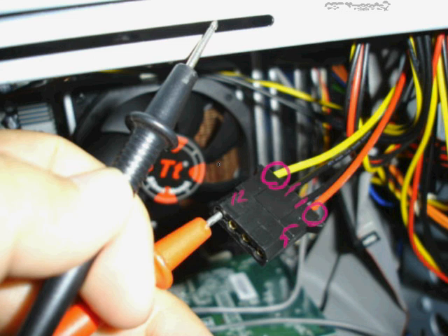and then it gave me a reading for how many volts was coming off of this Molex connector. Now, by the way, you might be saying, well, James, why didn't you take that probe and put it on the case? Why didn't you just put it in one of these grounds? Well, a couple of reasons. Number one, if I accidentally touch metal contact between the two of these, I can short it out and cause an electrical problem. Although it's unlikely, because you can see there's a round portion of these leads that prevents them from bumping into each other. But just as a precaution, any ground would do. So that's one reason why I chose that one.